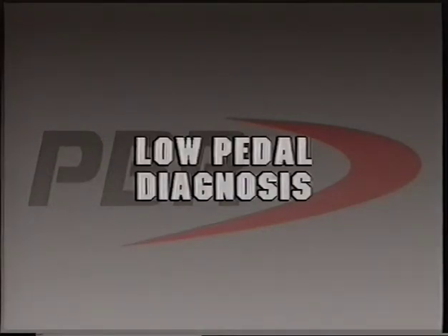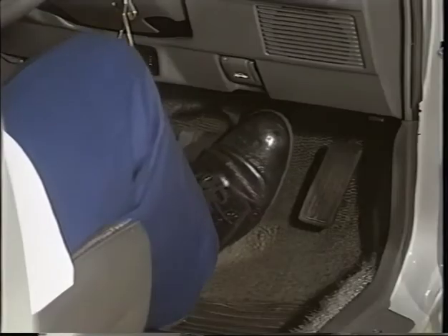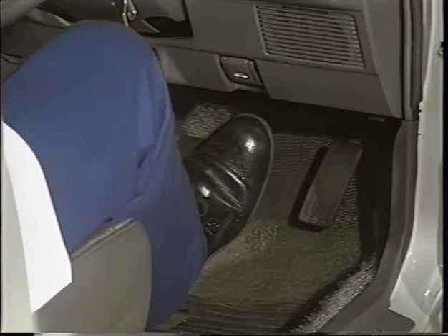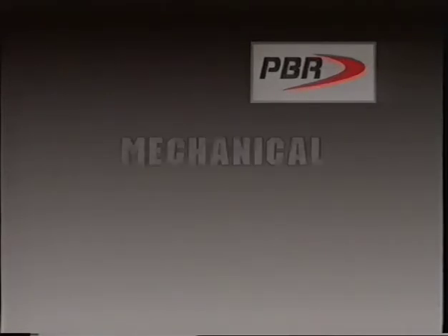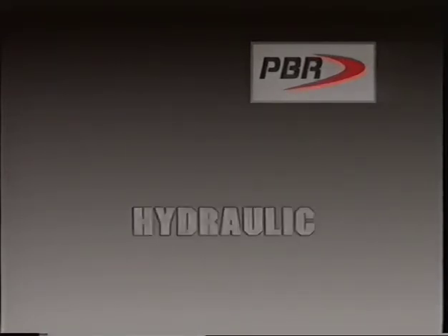This concludes this video on low pedal diagnosis, but before we leave, let's just recap on what we've covered. A low brake pedal is one that travels an abnormal distance and yet still feels firm. In some cases, its height can be increased by rapid pumping. Causes of low brake pedals can be either mechanical, hydraulic, or a combination of the two.